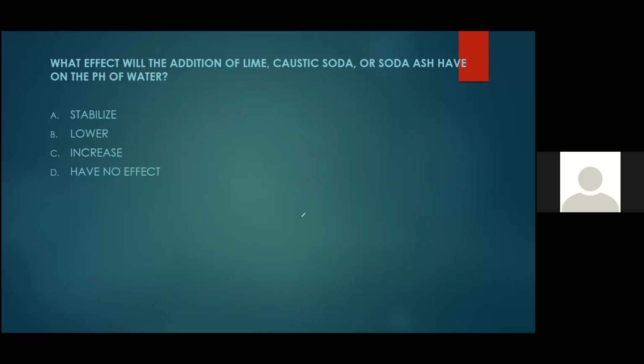One of the big things when we talk about pH is chlorine. Remember we talked about chlorine. Chlorine works well at a pH of about 7.5 because an acid is created and an ion is created. At 7.5 pH, there's lots of this acid stuff. And this is what kills that bacteria. That's the stuff, because it breaks down into an acid and it oxidizes the hell out of everything.